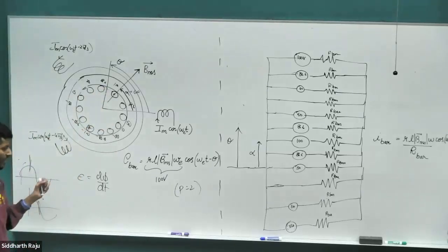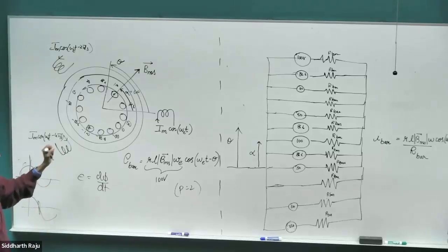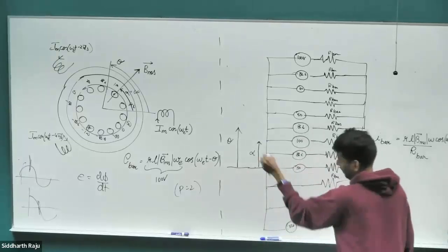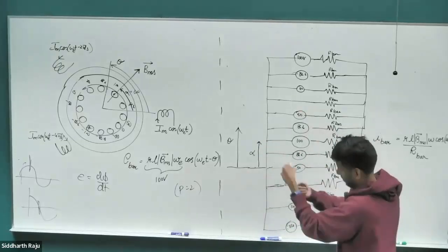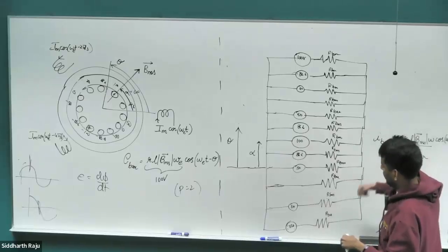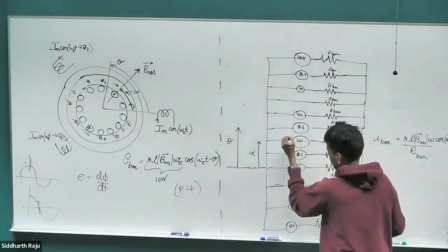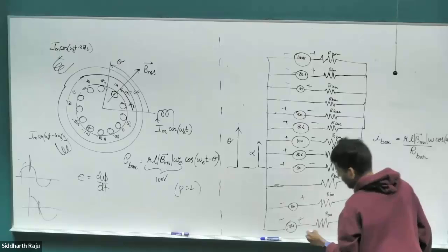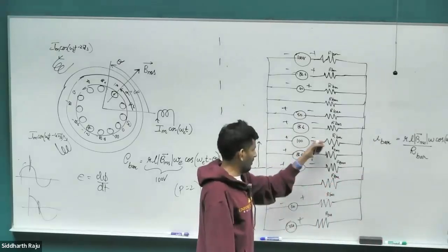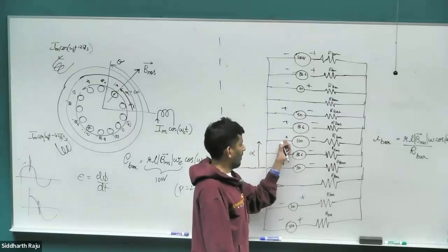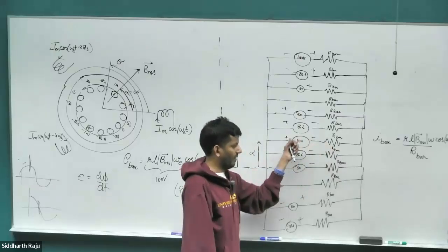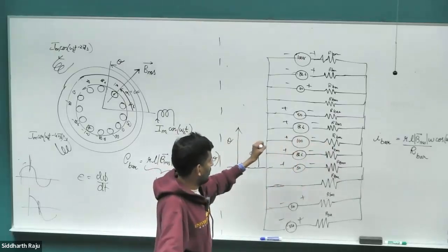And we have achieved everything that the stator has achieved without doing anything special for the rotor, with just a bunch of similar rotor bars. Because of this, we are going to have currents on the rotors, and we figured out how the current would come about. Whatever diagram I have there, I just put it in a planar form, just cut it open and look at it in a planar form. We have a bunch of voltages that have been developed across these bars. And to figure out the current through this bar, Ben gave the answer last time: if you take the voltage that's available across each bar and divide by its resistance, that will end up being the current through that bar. Again, this was quite counterintuitive to come up with.